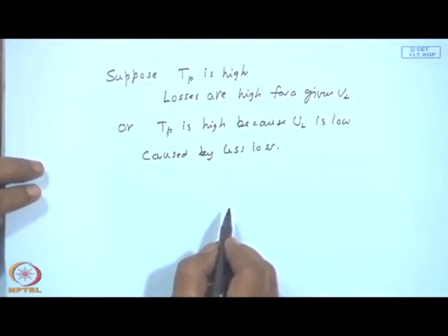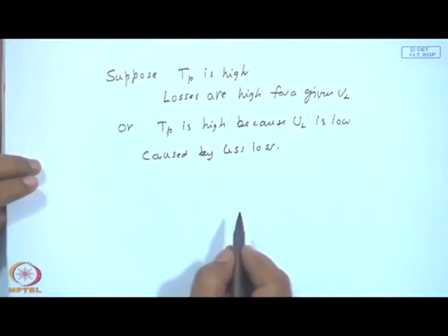If the collector plate temperature is 120, it may be an excellent efficient collector transferring energy to the fluid at a high level temperature, or it may be a poor collector since it is not able to transfer the energy to the fluid, so it is at a high temperature.